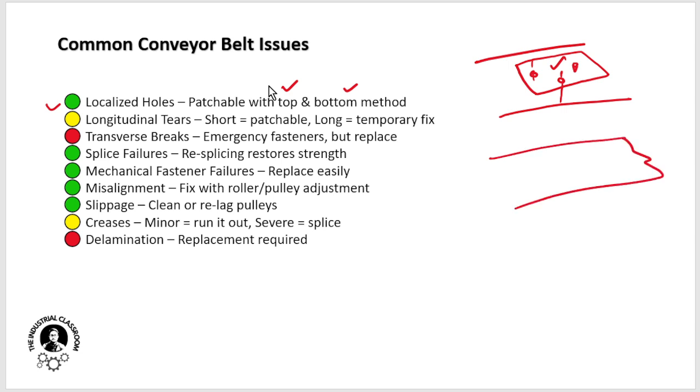Okay, this is your conveyor belt, and we have a longitudinal tear here of this length. Then we will generally repair it from the top cover or using a top patch, bottom patch. But if it is very lengthy, then repairing it is a temporary fix. We will generally go for piece addition, meaning removing this old piece and putting a new piece in its place, or we will go for a complete belt replacement. Or if there is much space in the take-up pulley, what we call the counterweight, then we will generally shorten the belt. So these cases are also repairable.